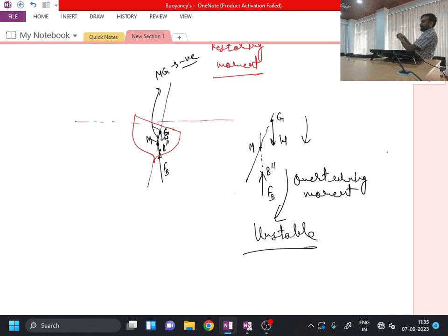in order to achieve stability, we want to keep the center of gravity in the deeper portion. So if I want to keep the center of gravity in the bottommost position of the object, I will keep the heavy portion of the submarine, such as its engine or other storage spaces, in the bottommost location. Okay. And another point is, as you are saying that we can change the volume, the outer surface of the submarine is a rigid body. It is not an elastic surface which we can inflate to change its volume. So from the stability perspective, the outer body is a rigid body.